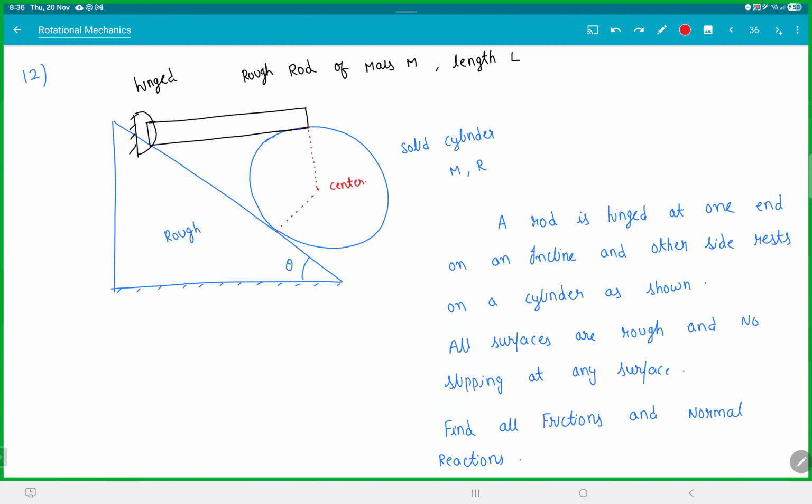Let's get them. Again, remember the process is still the same. Step one, choose a system, draw the FBD. Now there are two systems, you have to draw two FBDs. Apply force equations in x direction, y direction, apply torque equation, solve. The concept is still the same. I just made the problem lengthier and tougher. Let's go ahead with this. And others, do keep your cams on.